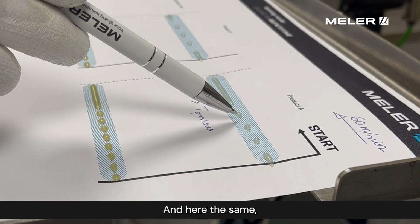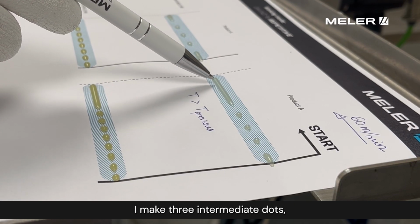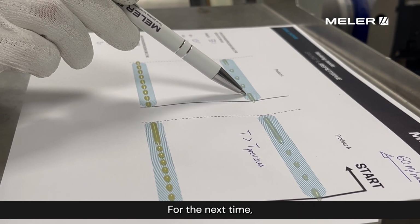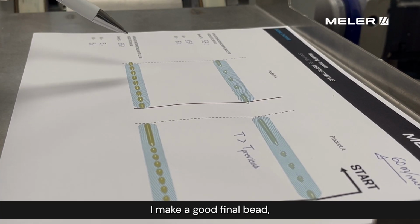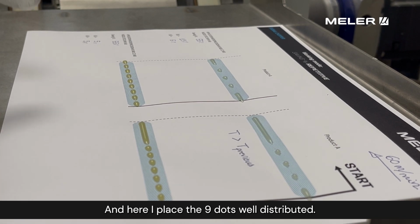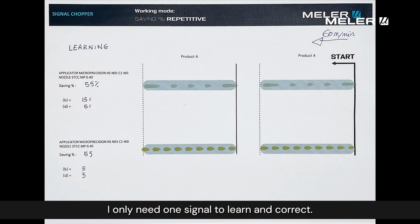And here the same. I make a correct initial bead, I make 3 intermediate dots, and the final bead is longer, so it gets stretched. For the next time, I've already learned. So I make a good initial bead, I make a good final bead because I already know where I'm going to end. And here, I place the 9 dots well distributed. I only need one signal to learn and correct.